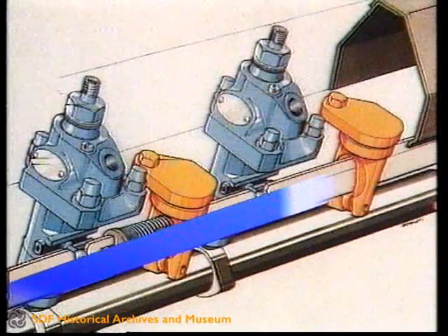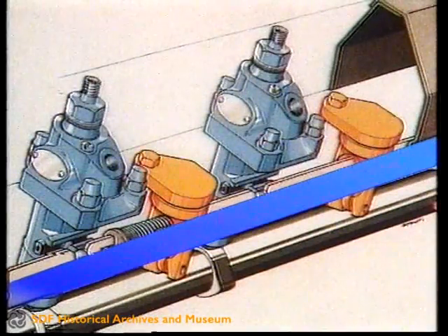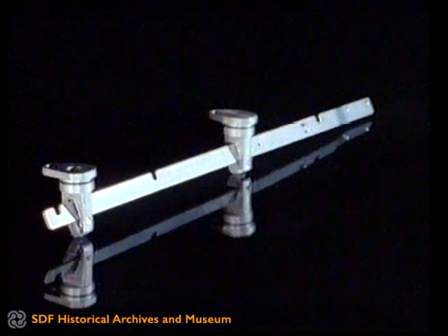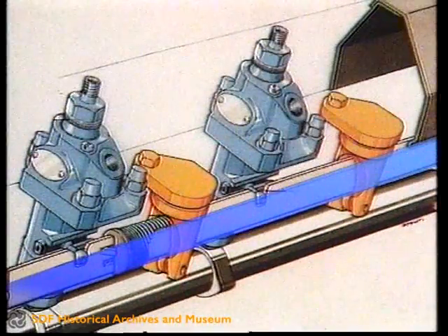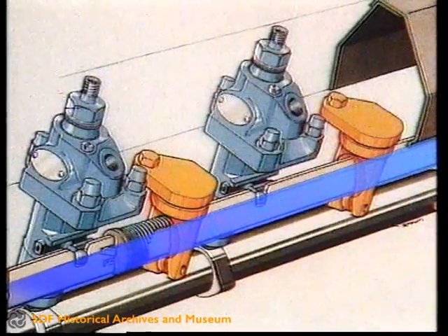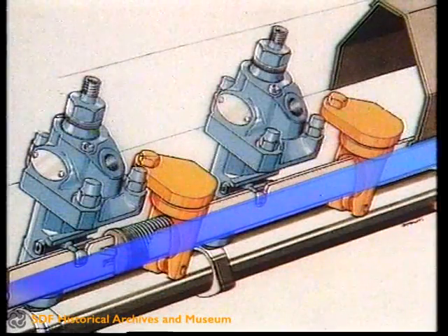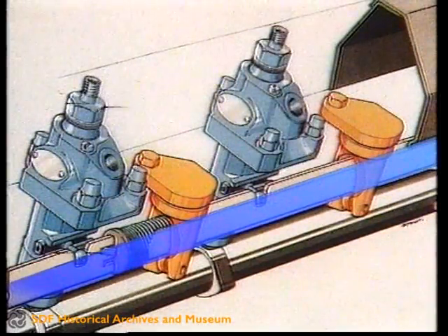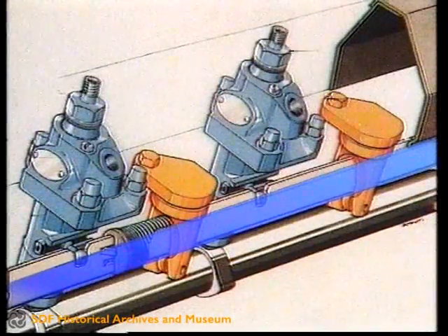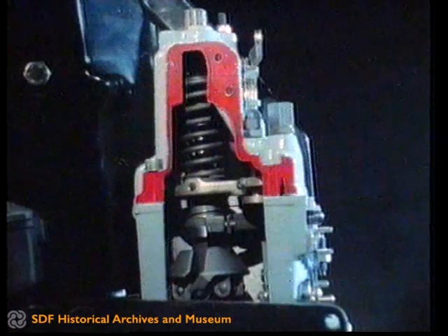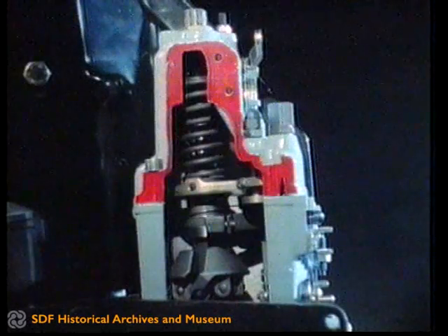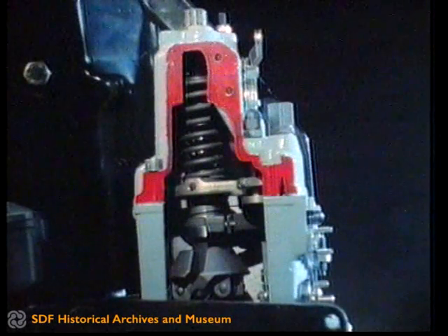The control rod, made of special alloy steel, runs on suitable rollers. Greater precision and sensitivity of regulation. The engine stop control acts on the regulating rod rather than on the regulator kinematics, thus allowing the engine to be stopped at any speed. Possibility of stopping the engine even at maximum speed, with the advantage of prompt action in emergencies. An anti-oscillation system contains the speed variations to within plus or minus 20 RPM during idling.